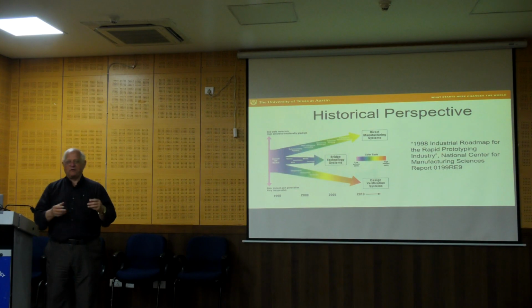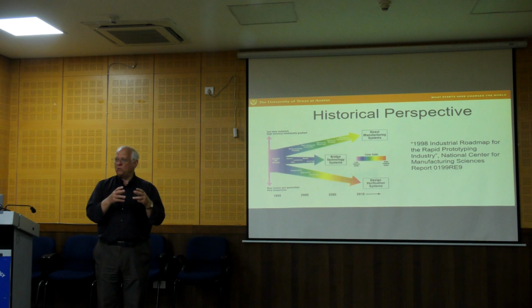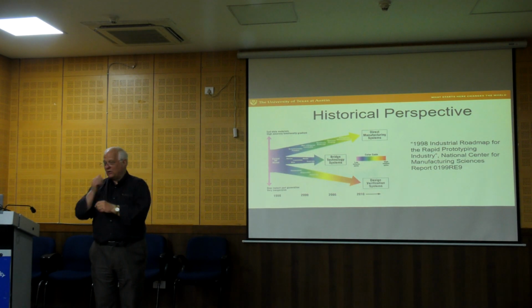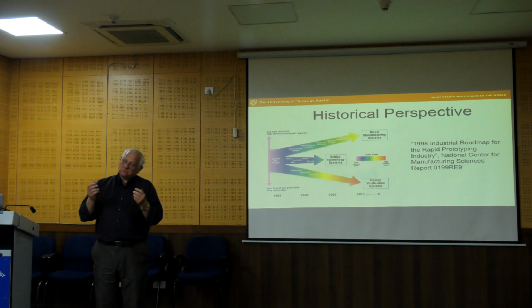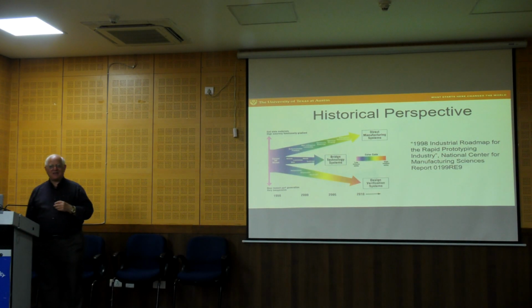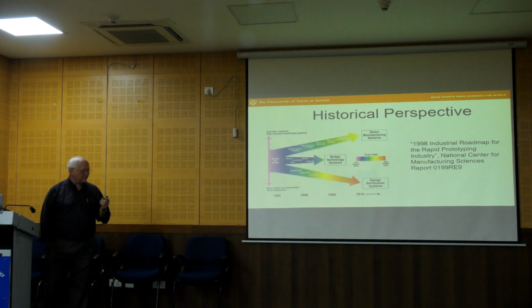And so, for example, the classic case would be using additive manufacturing to create a wax pattern, and then to use that wax pattern to form a mold cavity, like, for example, a lost wax type technology, and then to create a metal part. So this becomes a way to get to that level. And so the conversion technologies, those are also very applicable today.